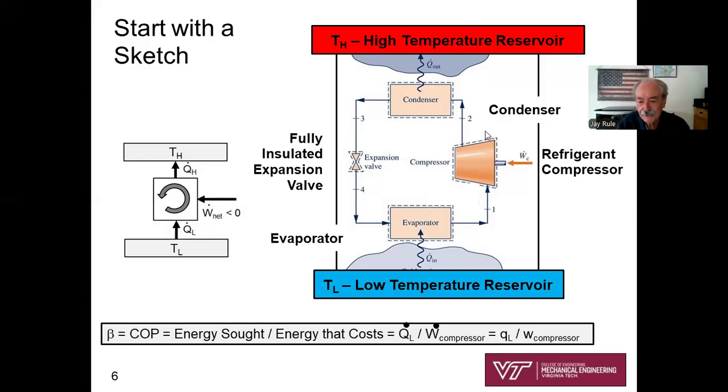Here is our compressor, steady state, steady flow, open system, one inlet and one outlet, operating reversibly and adiabatically. A condenser, it's just a heat exchanger, and it's exchanging heat with the surroundings. So heat is flowing out of the hot refrigerant into the surroundings. Okay, we come around here, steady state, steady flow, one inlet, one outlet. Expansion valve, fully insulated. It's got insulation packed around the valve.